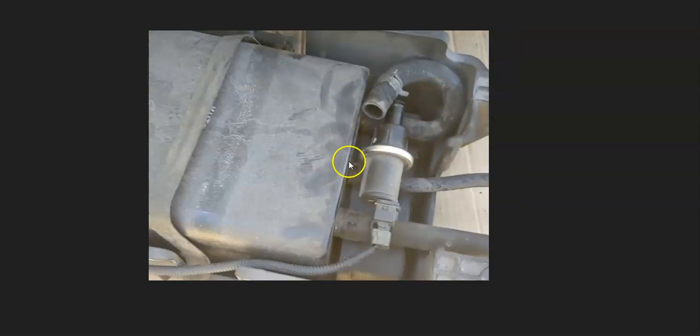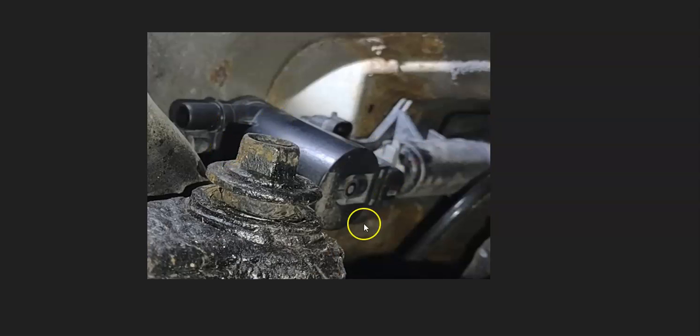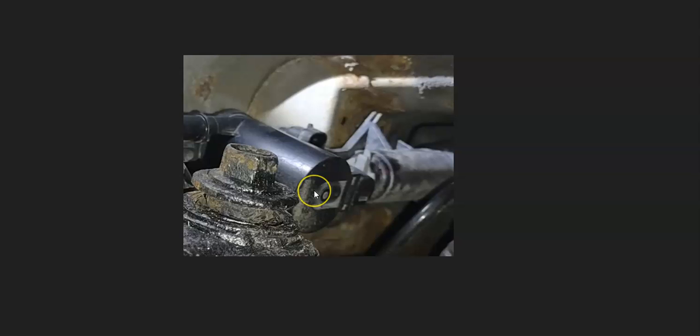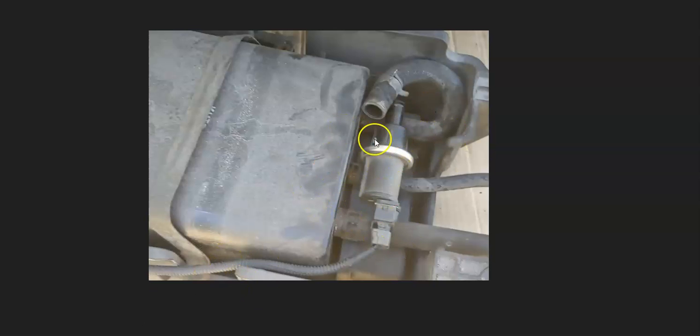For example, right here, this is a 2005 Kia, and it's built into the back of the charcoal canister. You take the charcoal canister off, and it's right there. And on this one right here, it's separate from the charcoal canister. The charcoal canister is over here, and the vent valve's right here. But the first thing to do is locate the vent valve on your particular Kia,